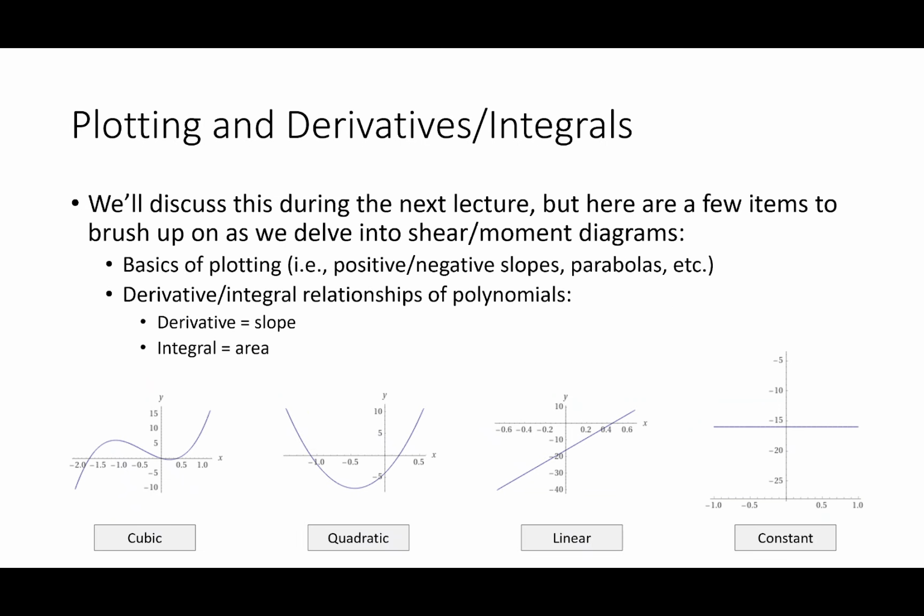If I had a cubic function and I took the derivative, I would get a quadratic. If I took a quadratic function, took the derivative, I would get a line. Take the derivative of this, I would get a constant. So if I have a 2 kip per foot constant distributed load, linear shear diagram, quadratic moment diagram. Now, whether the parabola is up or down, whether the line is this or this, we're going to get into that, okay? But being able to understand those patterns is important, okay?